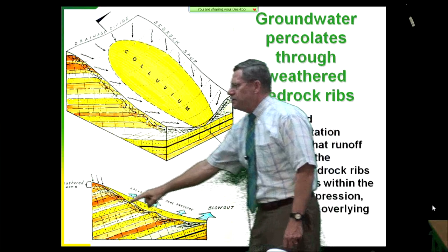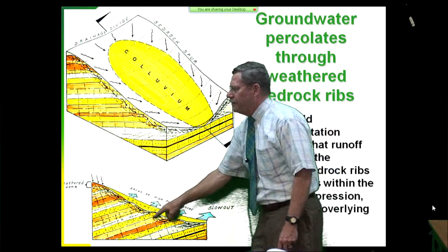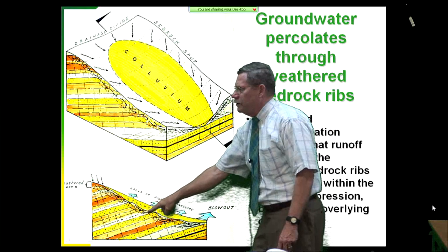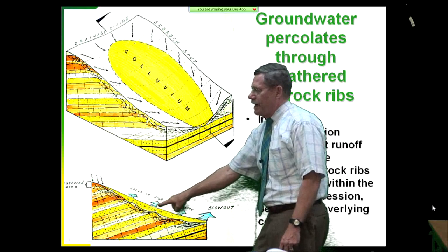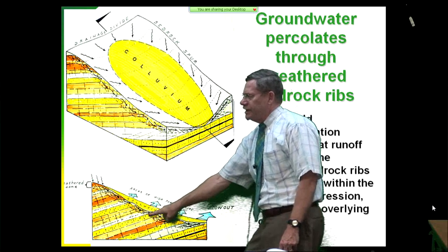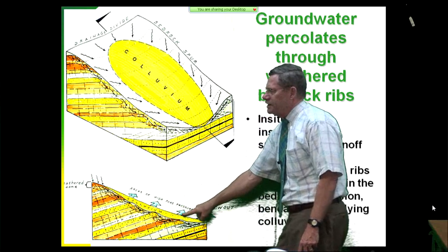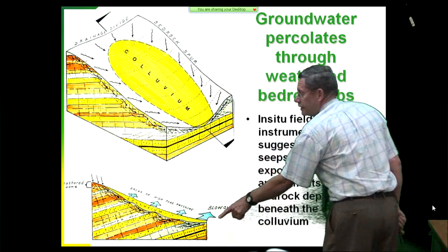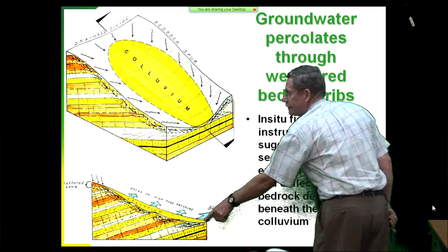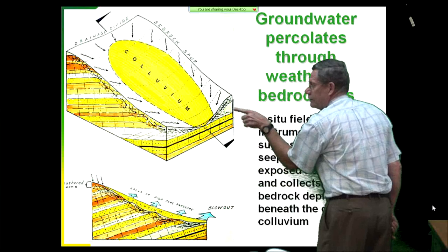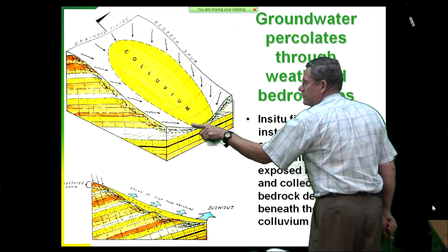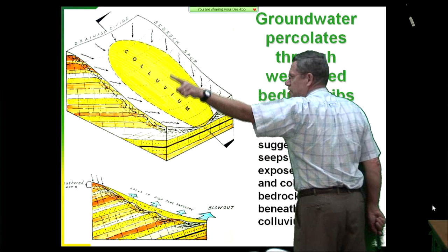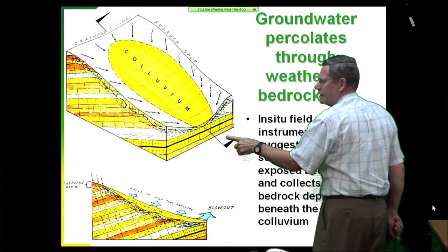And what happens is you get bedrock high points and bedrock low points. Where the colluvium's thicker, you can develop high uplift pressures because of these pinch outs by these resistant materials. And typically the blowout, the initial blowout that kills everybody, will occur right here where the pinching is most severe, because the accretion is most severe at that location.